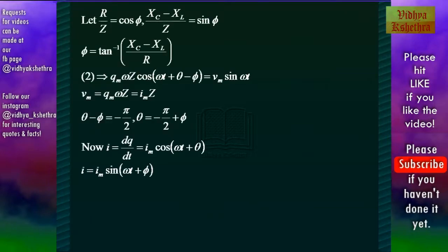Now let R by Z be equal to cos phi and (XC minus XL) by Z be sin phi. So phi is equal to tan inverse of (XC minus XL) by R. On substituting these values, equation 2 becomes, by using trigonometric identities, qm omega Z cos(omega t plus theta minus phi) is equal to Vm sin omega t.